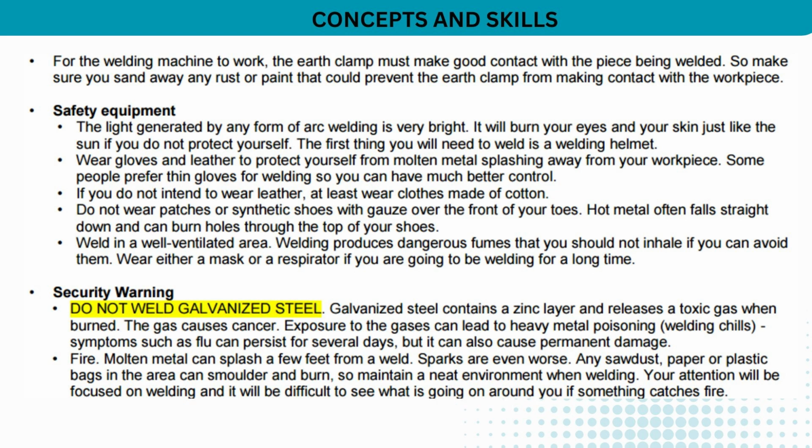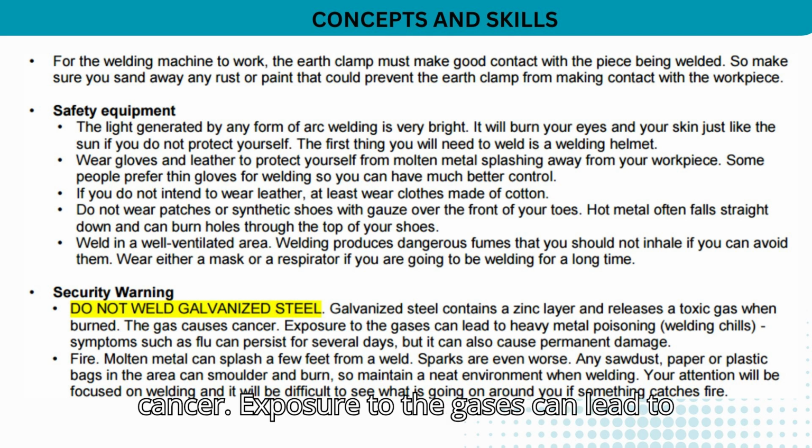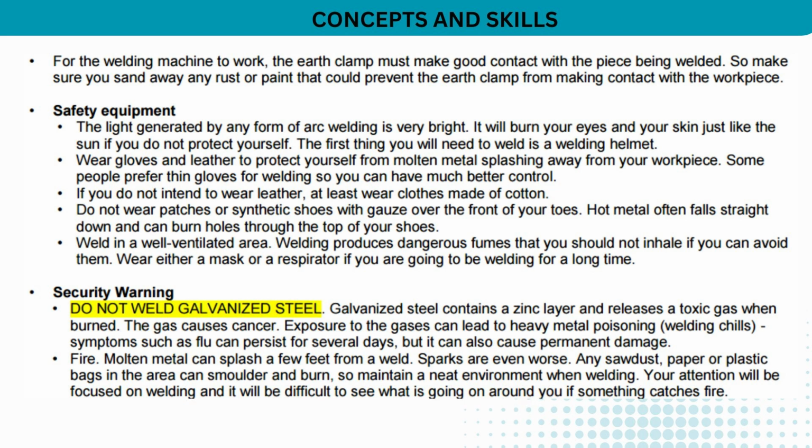Safety warning. Do not weld galvanized steel. Galvanized steel contains a zinc layer and releases a toxic gas when burned. The gas causes cancer. Exposure to the gases can lead to heavy metal poisoning, welding chills. Symptoms such as flu can persist for several days, but it can also cause permanent damage.